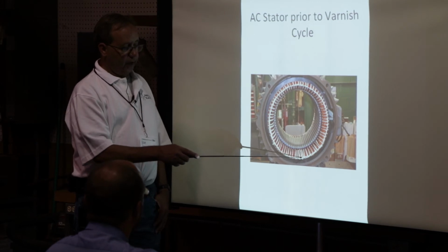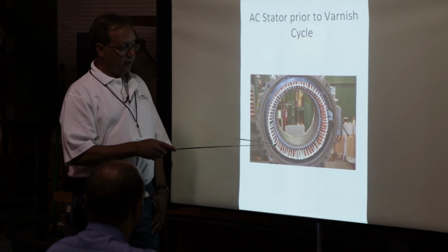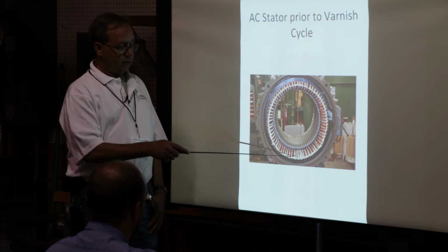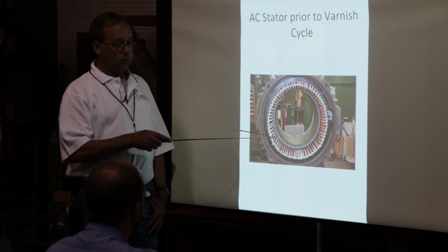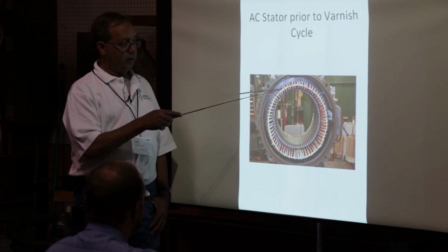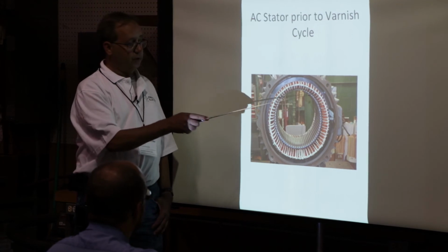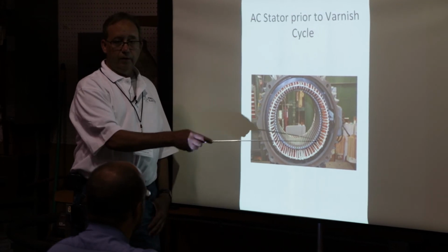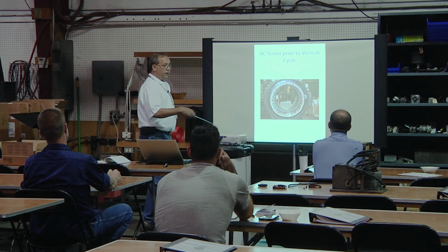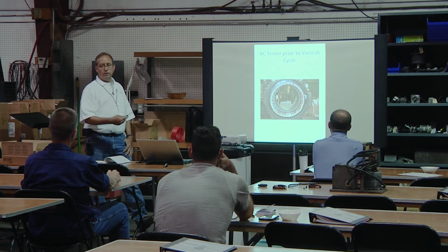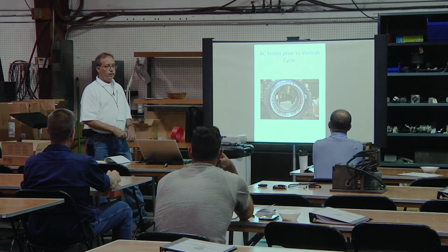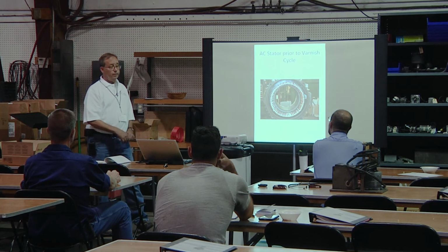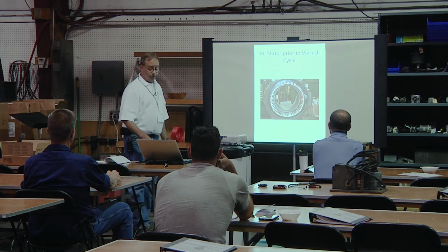So if we have a north pole here, south, north, that's 1 pole. North, south, north, that's the 2nd pole. North, south, north, 3rd, same thing. So that current is just chasing itself in a circle. And it'll do that whether you got a rotor in it or not. It pulls a lot more current without a rotor in it, but it will do it.